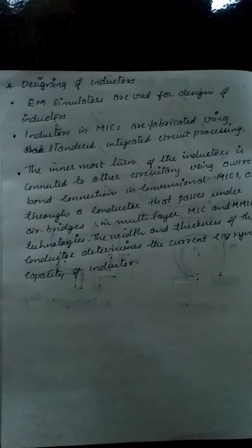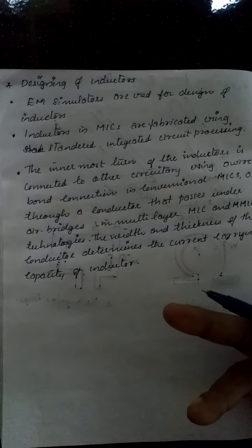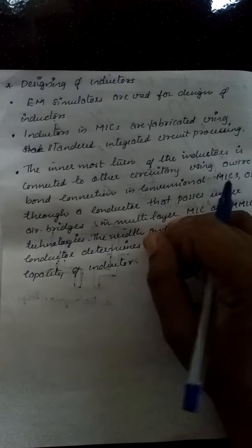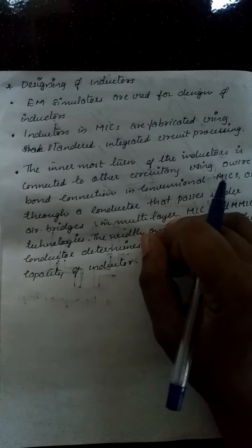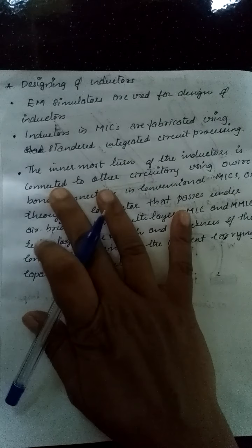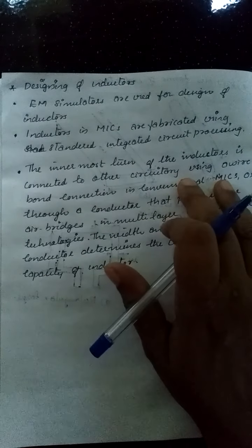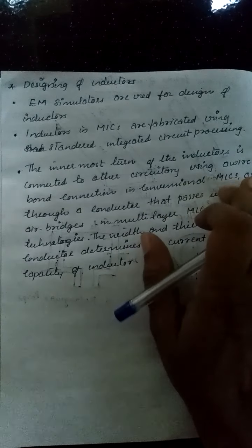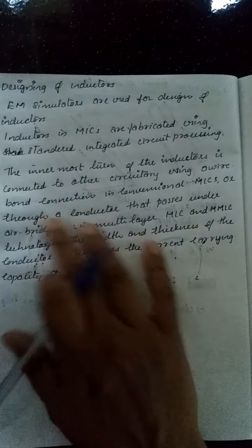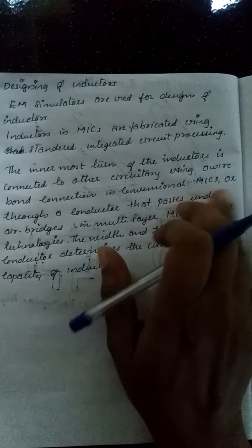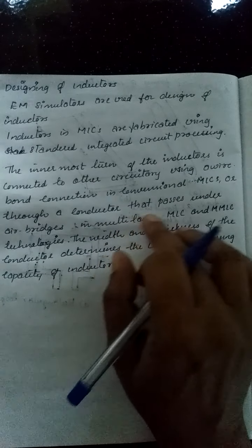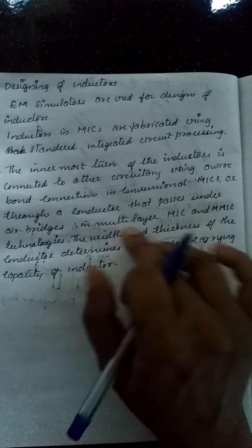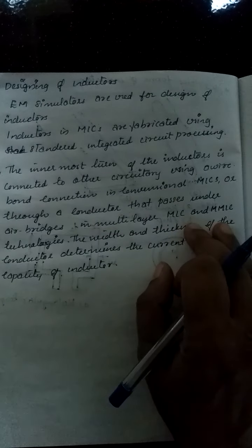Moreover, the innermost turn of the inductor is connected to other circuitry using a wire bond connection in conventional MICs, or through a conductor that passes under air bridges in the multi-level MIC and MMIC technologies.